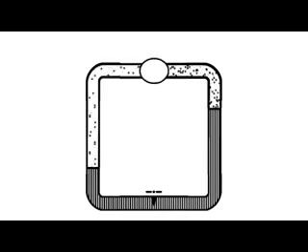Here we draw from our aerosol can example. On the high-pressure side, we are pushing, squeezing the gas molecules, forcing them into a liquid state. And on the low-pressure side, we are ripping the molecules out of their liquid state and into a gaseous state. We are condensing on the high-pressure side and evaporating or boiling on the low-pressure side.